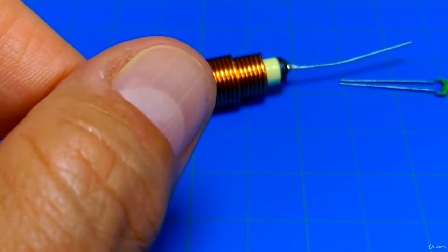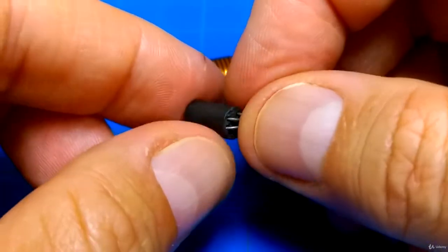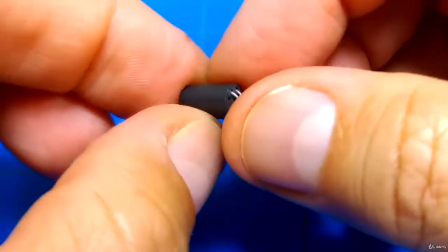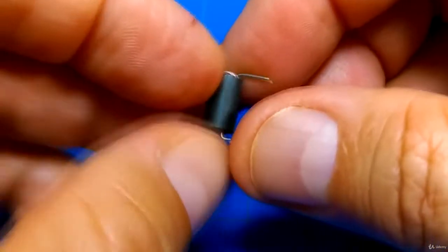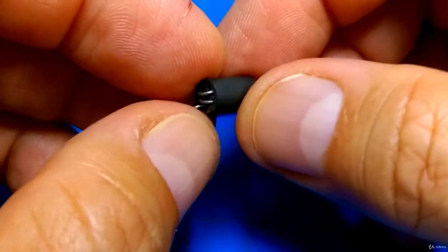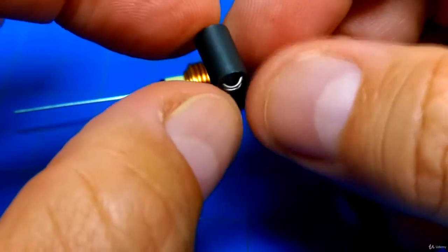Okay, so there's that. Now here's another one. This is another inductor, and this is called a ferrite bead. You can see we just got ferrite, this material, and then we just got a few turns in here, and then this goes in a circuit. These are typically to reduce noise, right? Because inductors have certain properties to signals, and they like blocking high frequencies. So this is good to block high frequency noise.